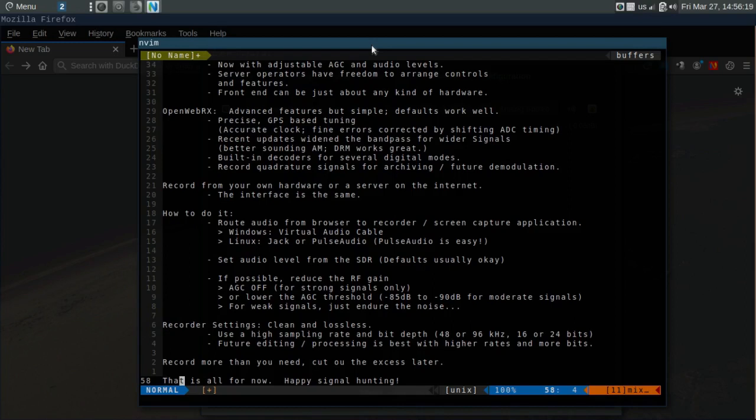The narrow filters can cause distortion on FM, and when you're listening to AM, if it's a broadcast station, their sidebands can go out as far as 15 kilohertz either side of the carrier. That's pretty wide. It's not good if it's a weak signal because there's so much noise with the wide filter. But if you have a strong station, go ahead and widen those filters out.